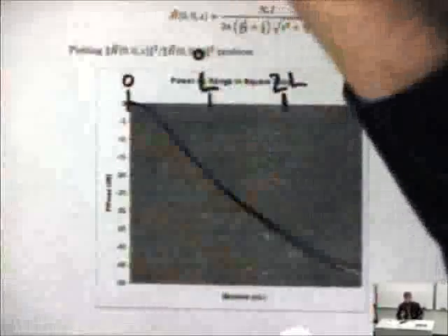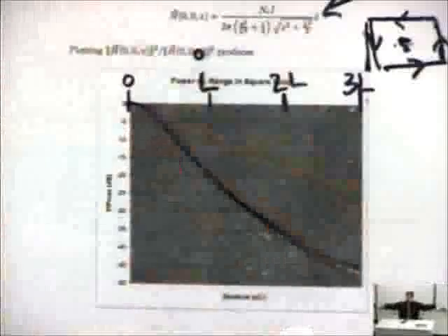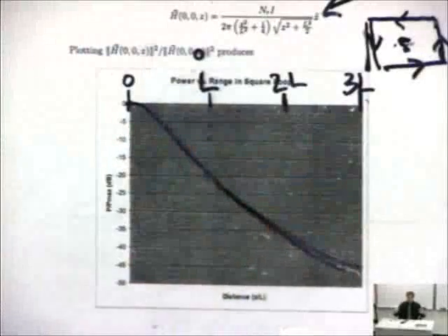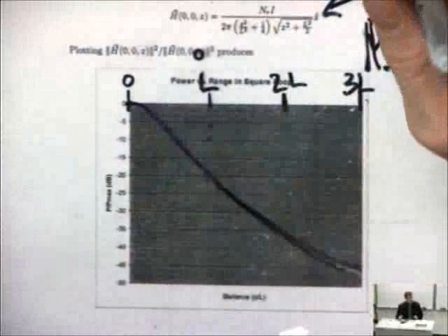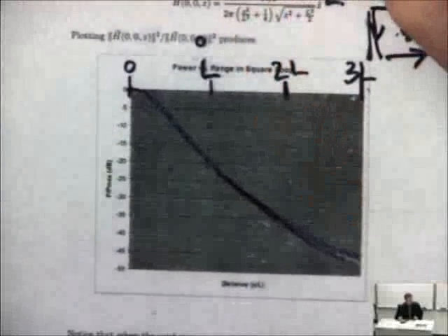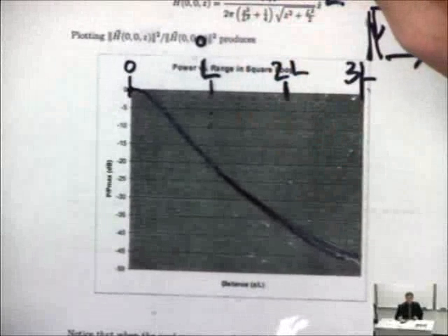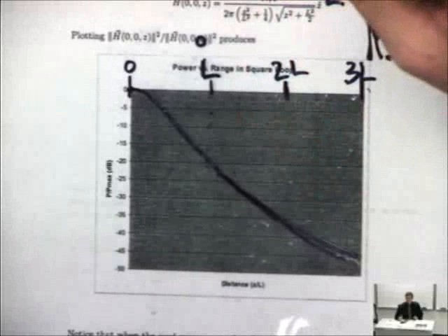So now you can see why this is so useful for near field payments, right? Or a MARTA card, or trying to read a MARTA card in a lane and not all the other adjacent lanes. Intrinsically, the mode of magnetic coupling is extremely lossy. If you double the distance, you incur 2 to the 6th loss.